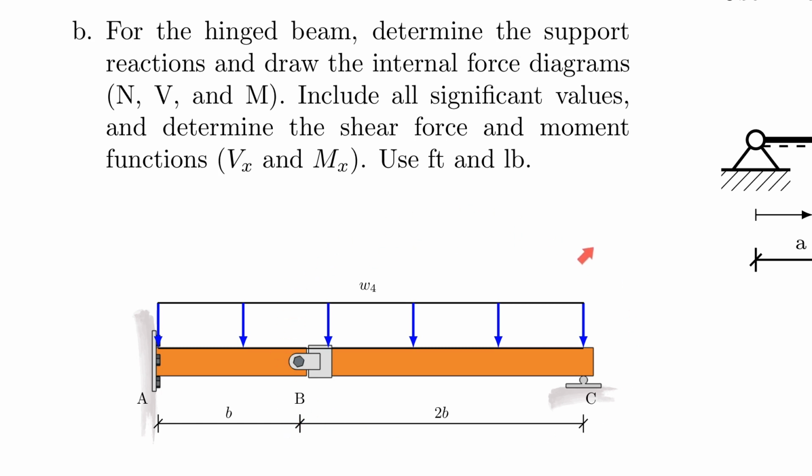For example, let's say you release the right side or you release the left side, whichever side you release, just treat it as an individual independent subsystem in which you then release the internal forces and calculate everything as you normally would do. So don't get confused by the image. It is all the same at the end.